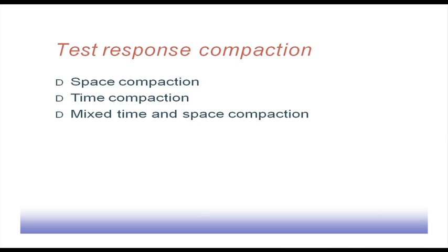Then we can have time compaction. So, time compaction is, maybe I am applying 10,000 patterns. Now, we do not want to remember all the 10,000 responses. So, we want to remember some summary of the whole session. So, that way the time compaction can be done, and there can naturally be a mix of these two.